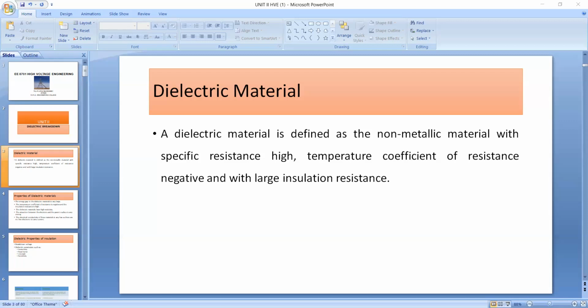The process of emitting an electron from a gas molecule with simultaneous production of a positive ion is called ionization. In order to understand Townsend's theory, an electric field is applied between the anode and cathode, and the electrons from the cathode collide with a neutral molecule and produce a positive ion and a new electron. These additional electrons again collide with other neutral molecules, and the ionization collisions repeat.